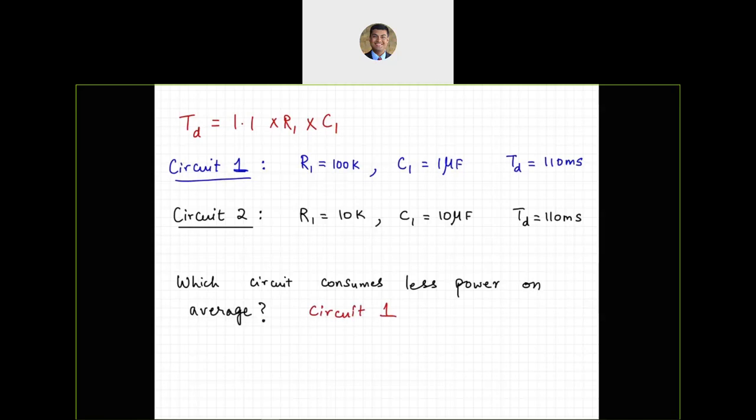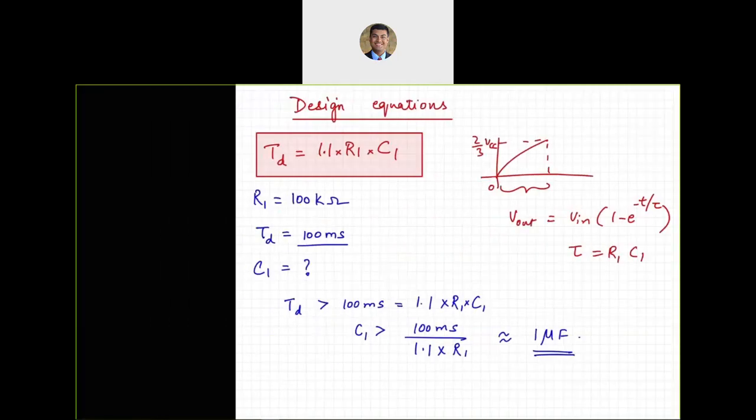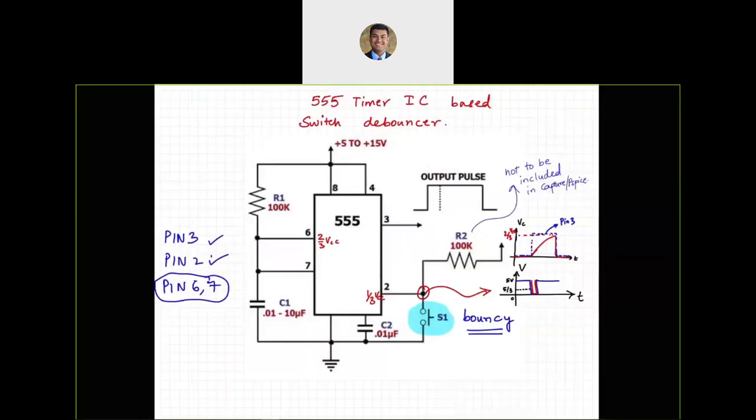The reason is there's a higher resistor there, which means that it's going to draw a smaller amount of current from the voltage supply. And if you look back at this diagram here, you have all these components. Whose power consumption are we monitoring? Well, we are trying to monitor the power consumption of that guy right there, the voltage supply itself.